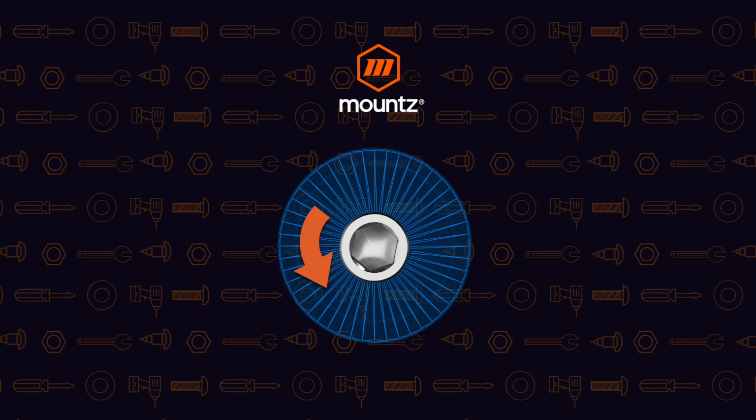But again, with the first movement test and with this test, and with what would be the next one, our marking test, it all gives us the ability to look at certain values based off of uncertainty and correlation to whatever value we receive when we do the test versus the value that we see when the original torque was applied. But the loosening test, again, is the least accurate of the auditing tests that you may see.